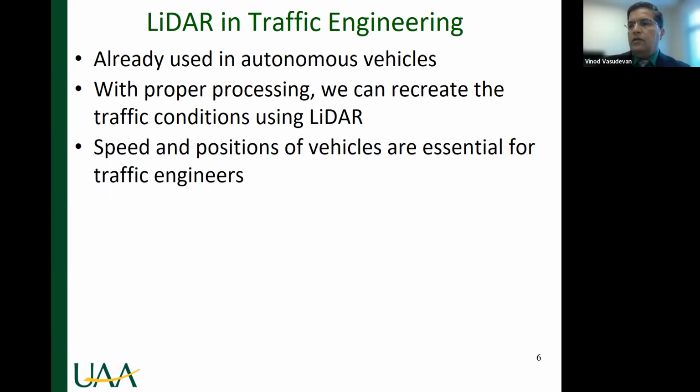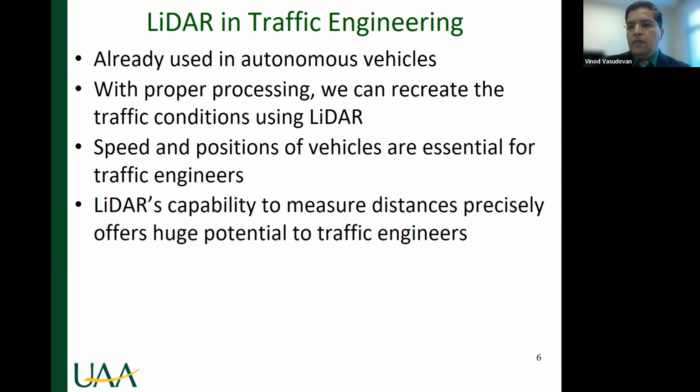Speed and position of vehicles are essential, not just vehicles, any objects are essential for traffic engineers. So if you can give me the speed and position of an object over a period of time, as a traffic engineer, I'll be very happy, because that's the information I want to estimate various parameters like density, speed, flow, etc. So LiDAR's capability to measure distances precisely offers a huge potential to traffic engineers. However, there are challenges. We'll discuss them.